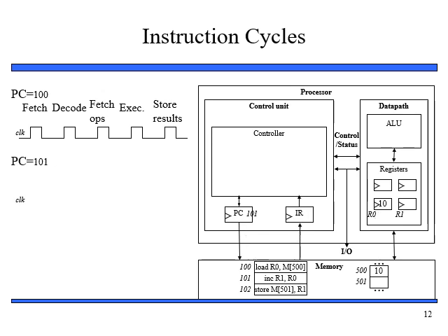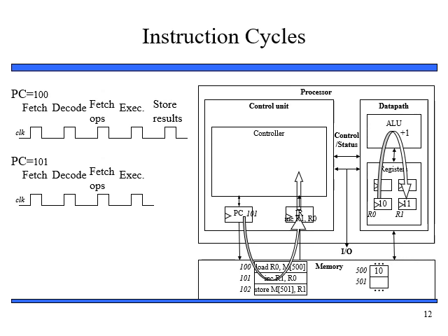Now the program counter automatically increments itself to the next instruction. In the first clock cycle, the instruction 101 will be fetched and it will go to the instruction register, as you can see here. In the next clock cycle, it will be decoded, what action we need to perform. In the next clock cycle, the operands will be fetched. The operands that will be fetched are increment R1, R0. In the next clock cycle, because we're incrementing something, we need to increment R0 by 1, and we will place the contents in register R1. You can see that R0 previously holds 10. The value goes to the ALU, it increments and stores back in register R1. Finally, we're not going to perform any store operation because the instruction is an increment.